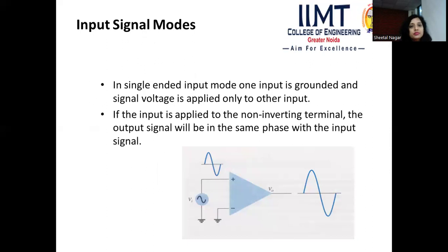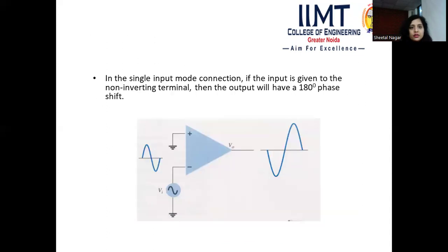Now, the input signal mode. Again, in this figure we are representing the input signal in the form of a sinusoidal sine wave, and in single-ended input mode, one input is grounded and the signal voltage is applied only to the other input. If the input is applied to the non-inverting terminal, the output signal will be in the same phase as the input signal, as shown in the figure also.